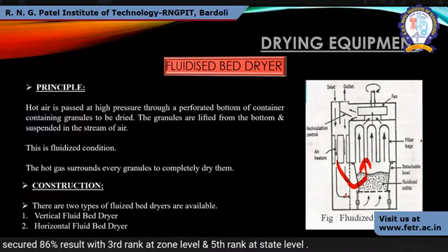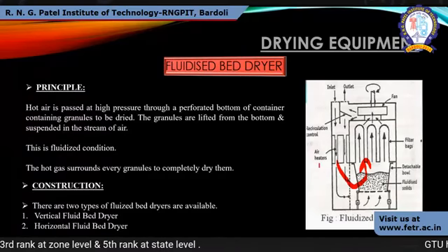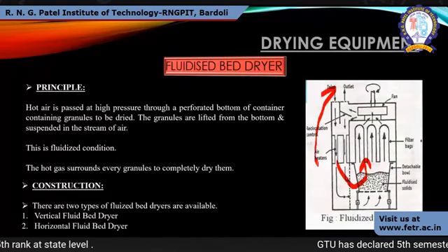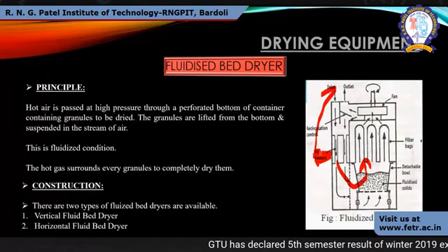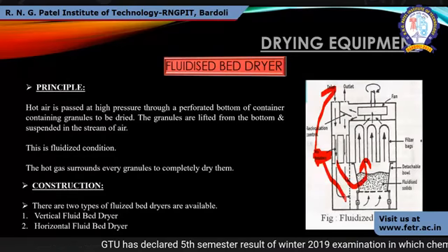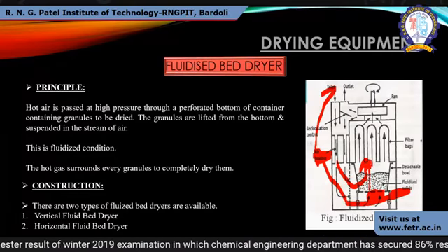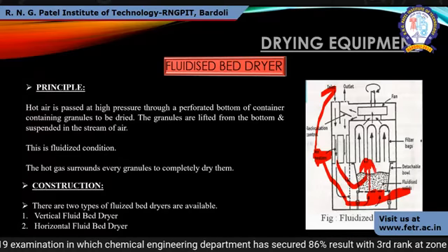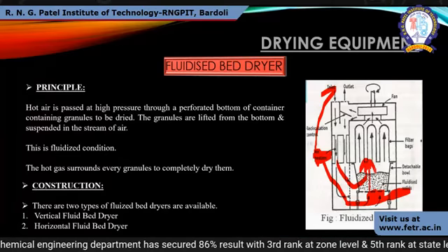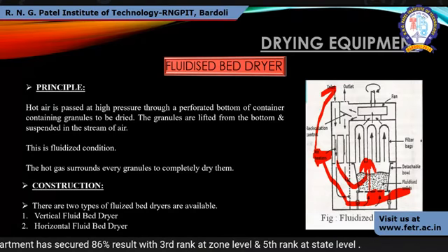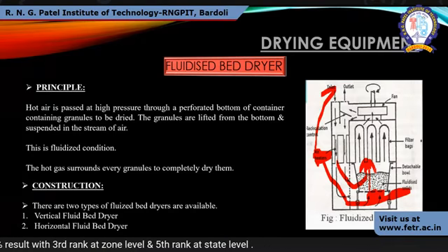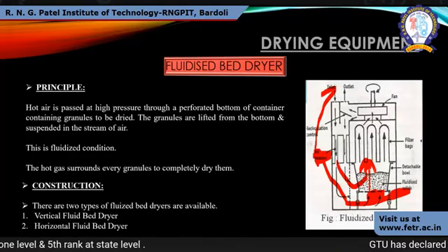We supply inlet air at very high velocity from the bottom, and the solid is in a fluidized condition, right? In that fluidized condition, each particle gets dried. So that is the fluidized bed dryer.